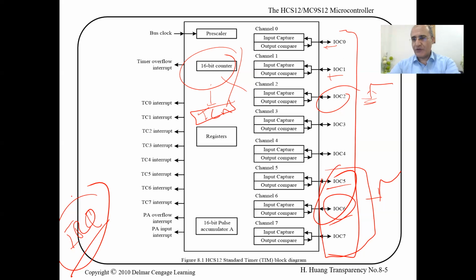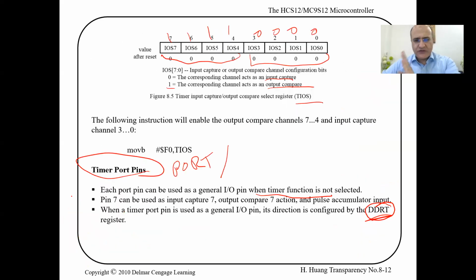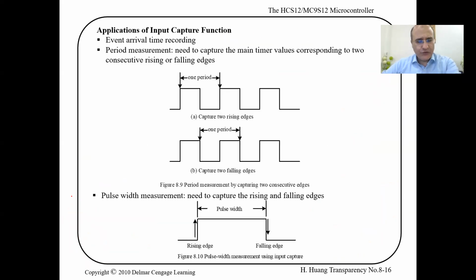You enable the interrupts locally in their local enable, and globally, write an interrupt service routine, use the address available in the interrupt vector, write what you want to do when this happens, then clear the flag before you return. This was just an idea on the side that it's just like you're having 8 extra IRQ interrupts.